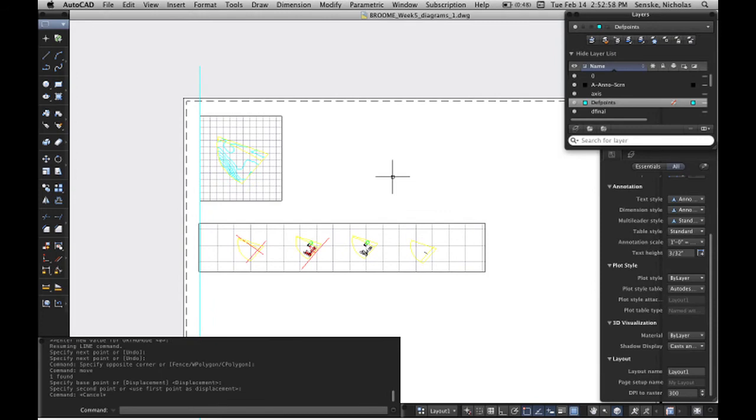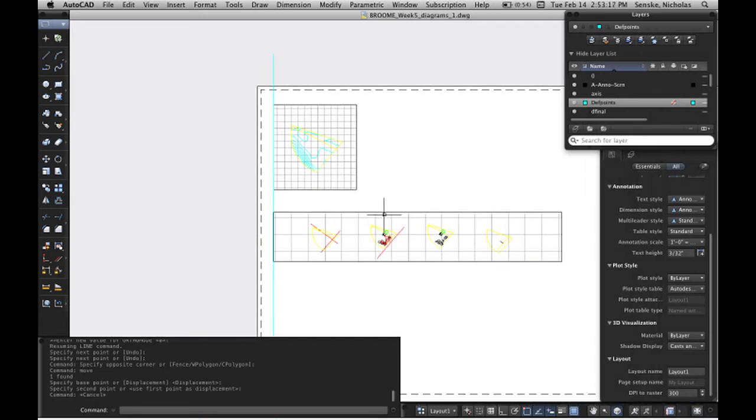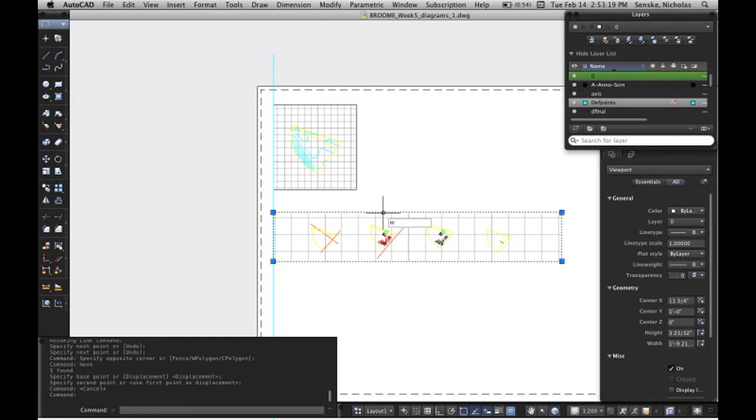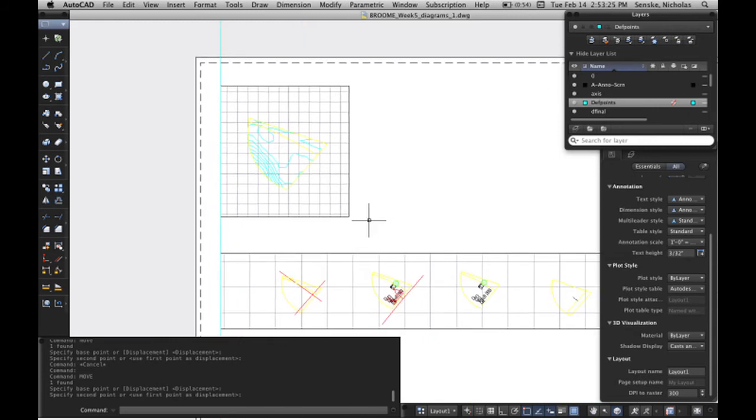That's a handy trick. So using the exercises that you guys did with Greg Snyder, you can draw really nice tartan grids to lay out these different kinds of proportions, and then put your windows in those proportions, and then use that to scale your elements. That's how you can really develop a really nice layout in AutoCAD before you get into Illustrator. It's a little bit easier, I think, than doing this all in Illustrator because you can align things with each other really well. You have all these really fancy snaps and move commands.